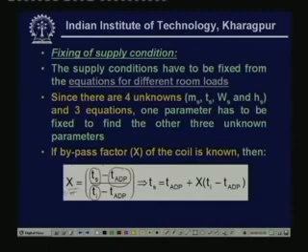Okay, so this is based on the definition of bypass factor. So from this equation you can write Ts is equal to TADP plus X into (Ti minus TADP). Now, X is known to us, it is specified by the manufacturer, let us say. Ti is known to us, and TADP we have obtained by extending the RSHF line to its intersection with the saturation curve. So this is also known to us. So, we can find out the required supply temperature. Okay.